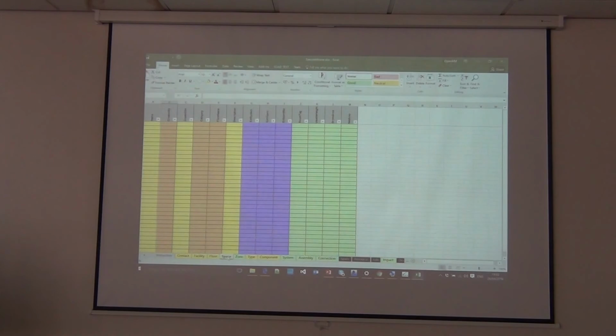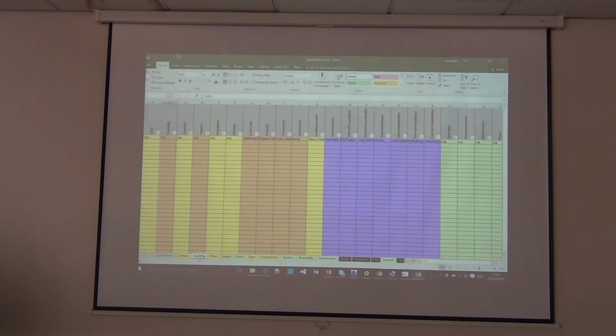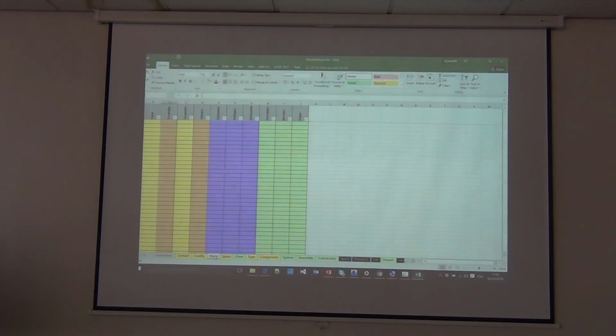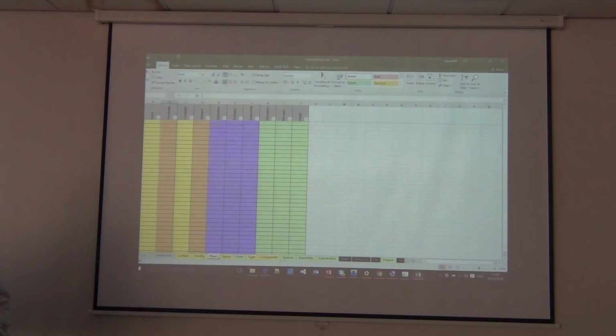I go and look at the spaces. It's got contacts. That's got that right. Better than the other tool, yeah? Because the other one didn't have my name right. The facility is not right, and the floors don't exist because Revit doesn't have floors. Okay. So what's happened? The reason this is like this is that Revit to IFC knows it's got to create floors and it's got to create spaces. Okay? Revit to Cobie doesn't go through that process, so it doesn't know.